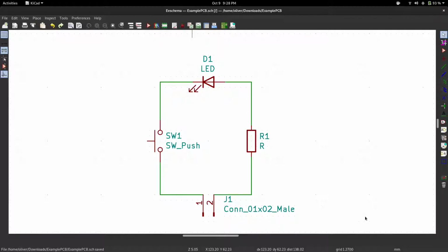One of them is plus, one of them is minus. This schematic symbol has no association with that until we give it an association with that. And obviously, different LEDs have different footprints on the board, so we need to assign a specific footprint to each schematic symbol based on what exact component we're using.